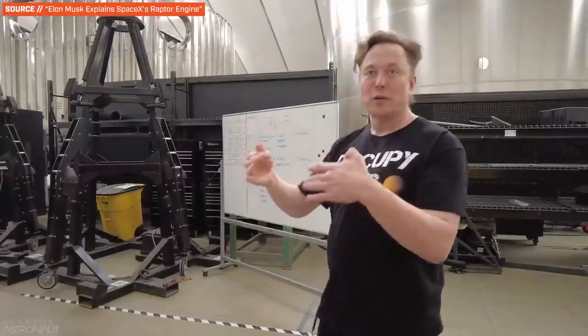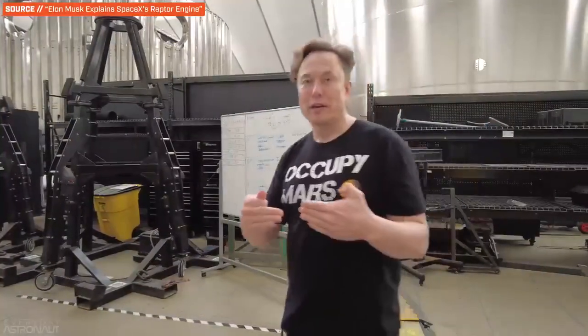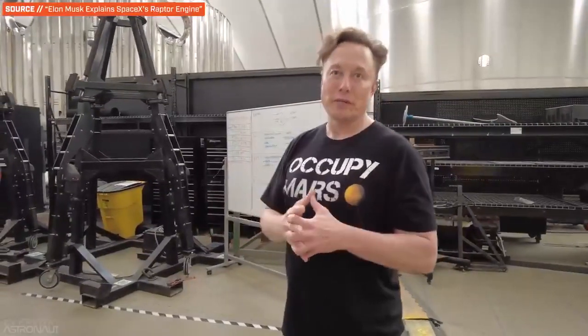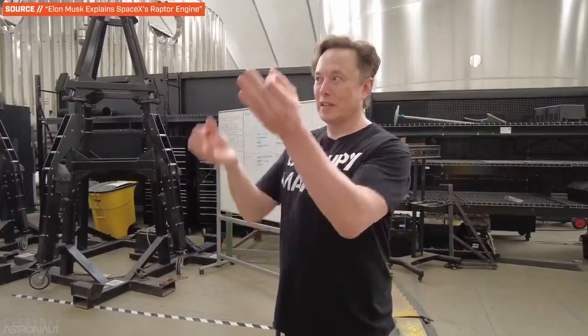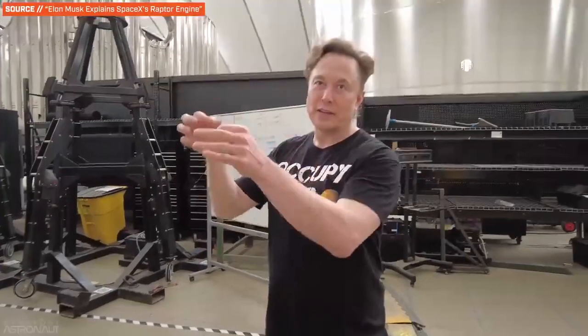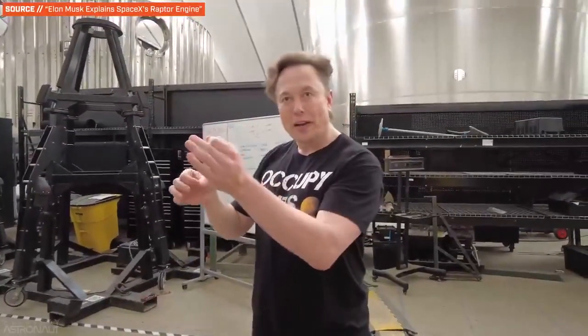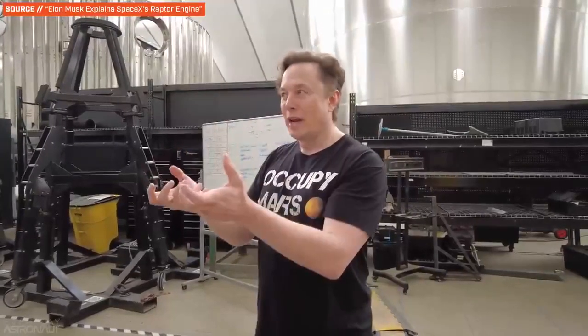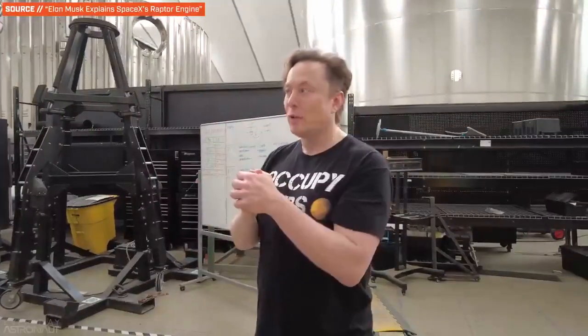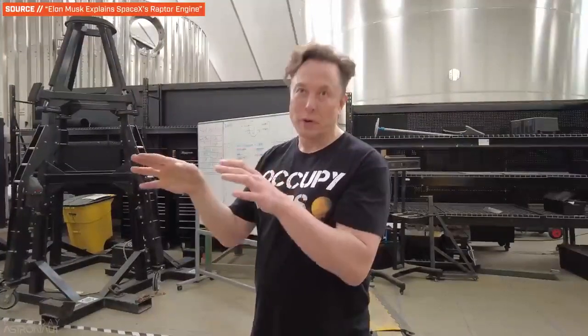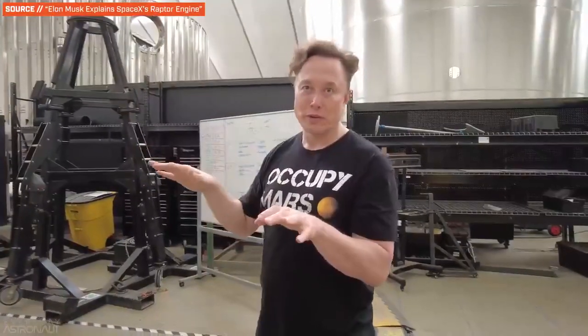Yeah. So the start sequence for Raptor is insanely complicated compared to the start sequence for Merlin. It has to be perfectly precise. You're doing this delicate dance between the fuel power head and the oxygen power head. And if they get out of sync, then you can go stoichiometric in the preburners and melt or explode the preburners. Yeah. This means managing the timing of valves, startup, and even throttling is extremely hard to master and requires some very deep pockets to perfect, which is why we haven't seen that many full flow engines developed.